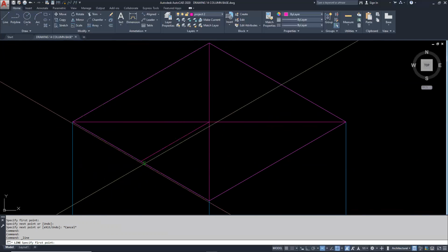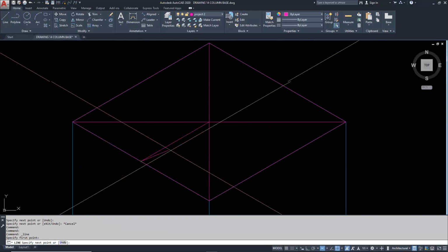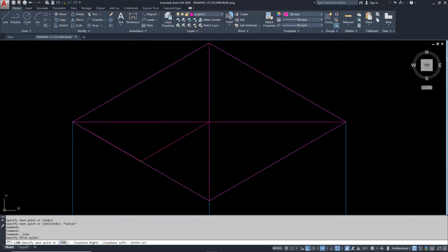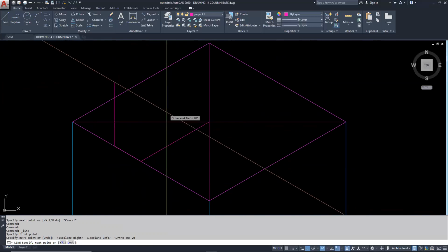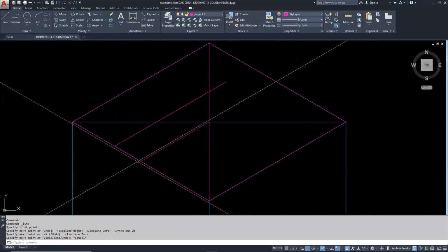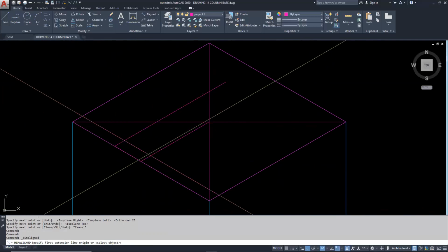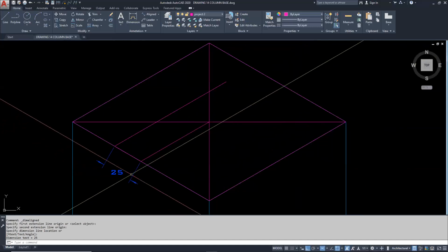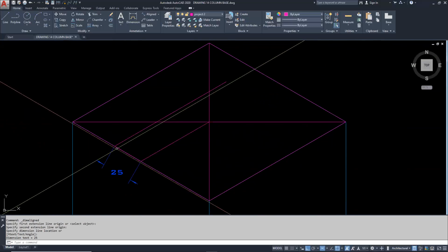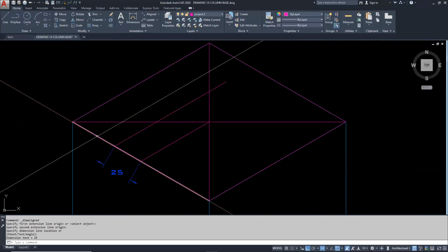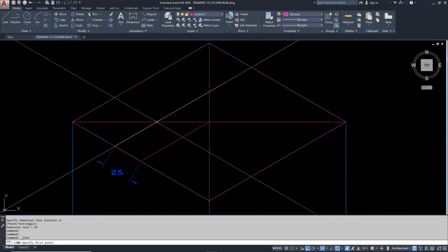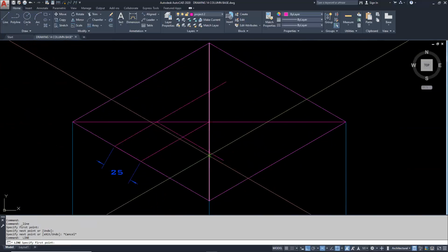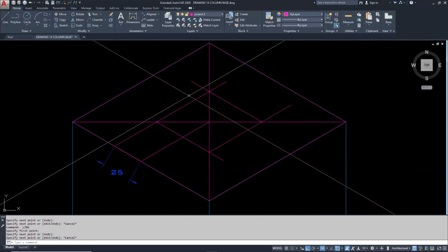and I need it to be 50 over. So what I can do is go from this point and hit F5 and F8, there you go, and get 25 over, and then hit F5 again to go this way. So what I did was I went from this point over 25. Let me put a dimension on there so you see it. 25. So once I found the center and I hit this line, I went 25 over, and then I projected back along the axis that way. Now, all I need to do is keep on coming around and hitting the points on the X.